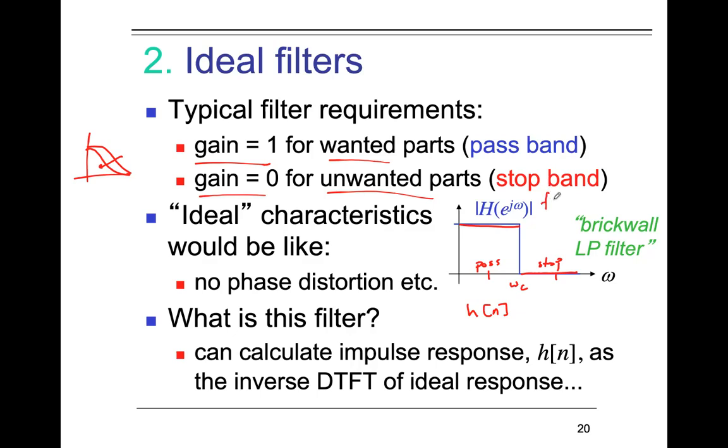This is the frequency response, the magnitude response actually. Why is it magnitude? Because we have the magnitude here, right? This is the frequency response and this is the magnitude response. How do you come from here back to h of n? Inverse Fourier transform, right? We use the inverse Fourier transform.